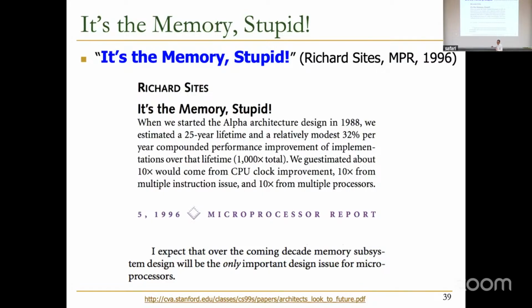And in the end, he wrote this paper saying that this processor is capable of finishing 4 instructions every clock cycle. Clock cycle is short, and 4 instructions is superscalar, right? At the time, we're talking about the 1990s. Unfortunately, on this important set of workloads that we think we designed it for, it's finishing 1 instruction every 4.7 cycles, every 5 cycles, let's say. So it's not finishing 4 instructions per cycle, it's finishing 1 instruction every 5 cycles, meaning it's operating at 5% of its peak throughput. Why? It's waiting for data to come back from memory, even though it has huge caches for the time being.